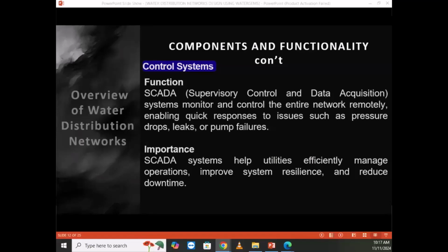Unless you do a pressure test from here and also calculate the flow coming from here, there is no other way that you can get the pressure and the flow. So the only way of having those data is to map this upstream, at least from the first tank of the upstream where water is coming. Map from there.